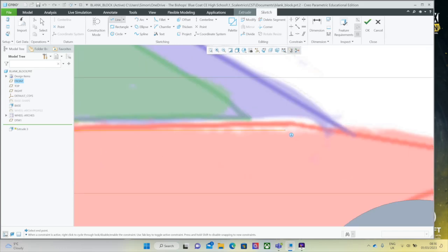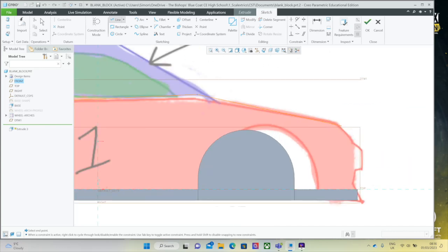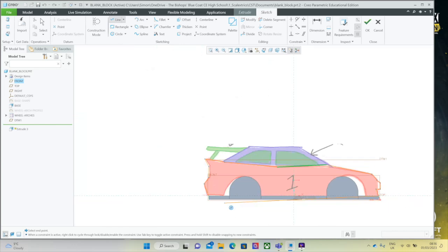I can use my scroll wheel now if I want to zoom in. So I'm just going to change that bit slightly there. Down to the front. We'll come in a little bit and then we'll bring it back there. Now you can see this is what we call the tail. I need to connect that to the other end and I'm left with another tail. To get rid of that, you click the scroll wheel. It now disappears.